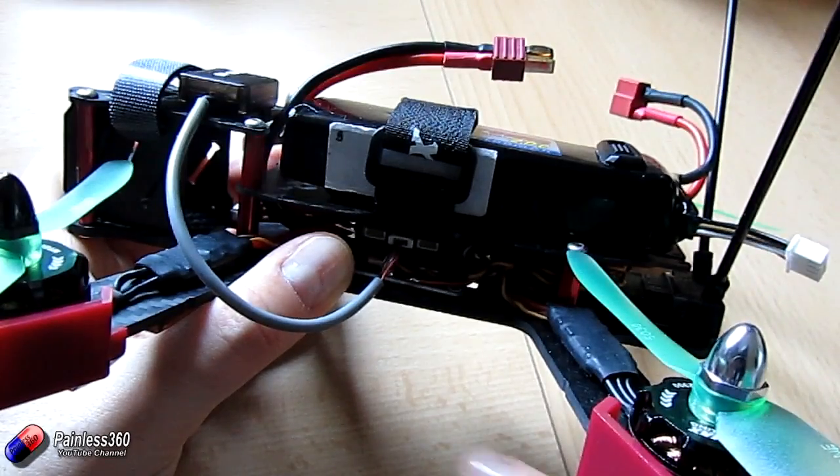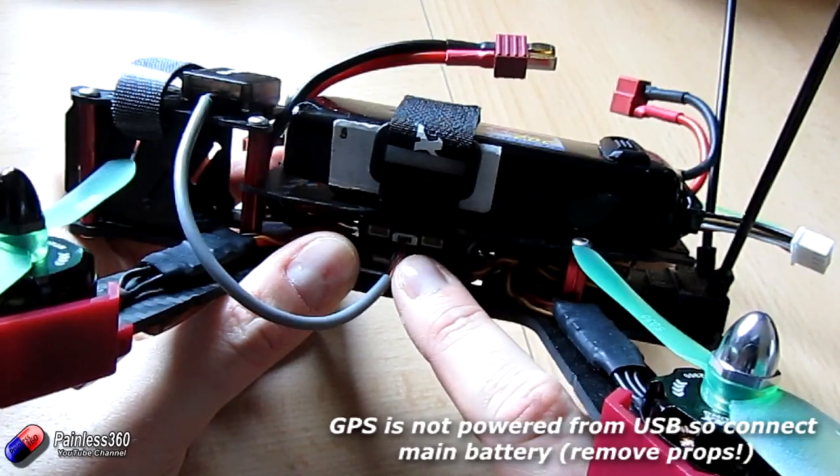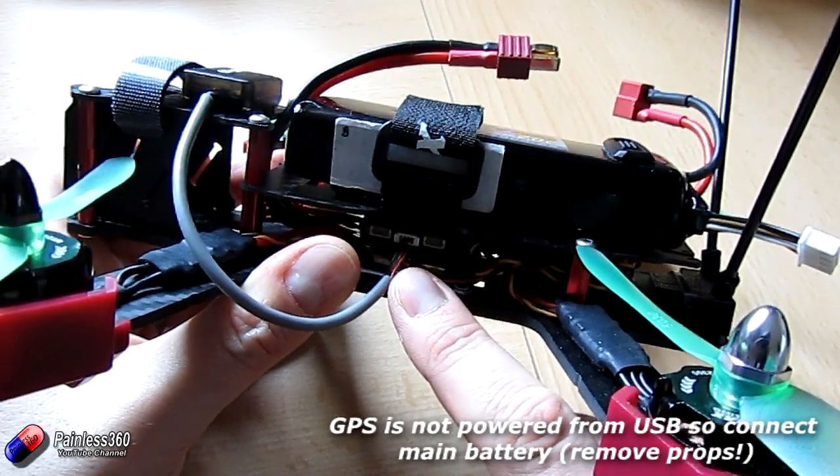So the first thing we need to do here, of course, is plug the GPS into the flight controller. We can either go into the main port or the flexi port. I've put it in the middle port, which is the flexi port.